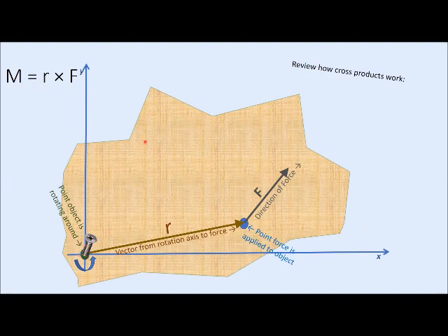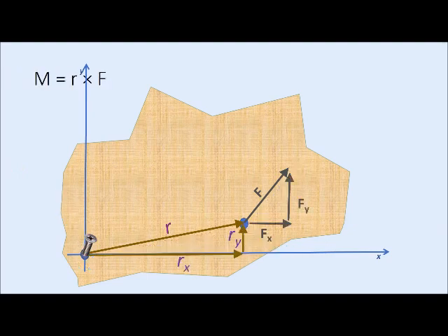So what we're going to do, say this is a big piece of plywood or something, and we're going to be rotating it around this bolt. Okay, so we have a nail or a screw or something in the plywood, and then over here, this is where the force is applied. So someone is going to be pushing on this board over here, and it's going to try and rotate it around this bolt. So we're going to see what kind of rotational motion this R and F combination are going to create. The first thing to do is to split everything into x and y components.